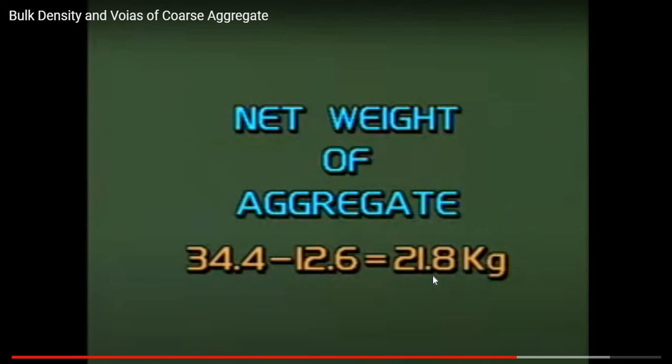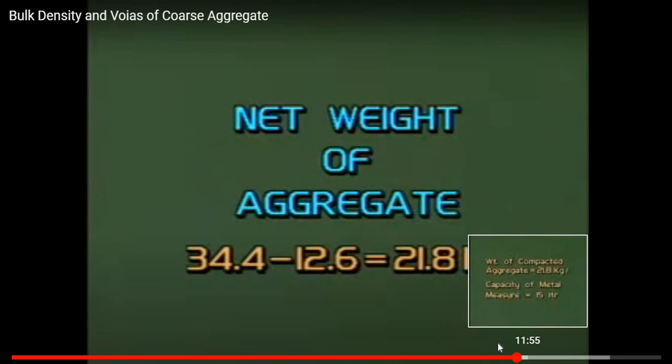Why did this happen? We used the same container, right? Why is there an increase in the weight of aggregate? Because in the loose aggregate there were more voids present, more gaps present, whereas when we compacted, we removed the air voids and the gaps where the air voids were got occupied by more aggregates, due to which the weight of aggregate has increased, because the voids have decreased after compaction.